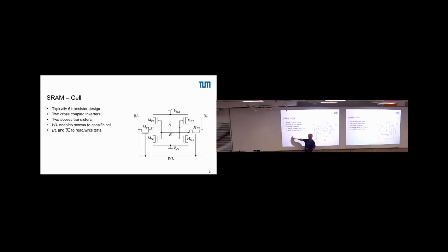You can just cheat and look at what happens. Well, the output voltage should stay here until the input voltage reaches this VTHP, right? Then the output voltage should go down and end up here. It's exactly the same curve, just flipped. This is actually VA over Vin. Just that I draw now Vin as Vin dash, and VA in this direction. So it's exactly the same. Okay? Good.